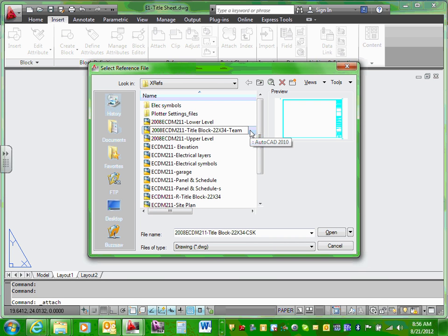One thing, Darren, don't change the title block name at all, because if you change the name after you Xref it, it will disconnect itself from the file. You can't see it anymore. That's why it's important to keep the name as is. Don't move it away from its location. Can we put our team number on there too? You're inside your team folder. So if you say team, this is your new partner.